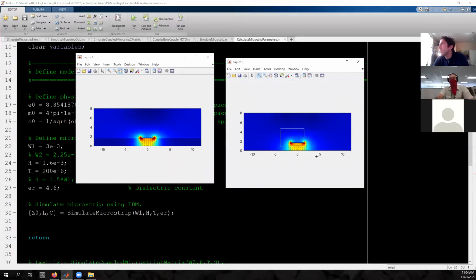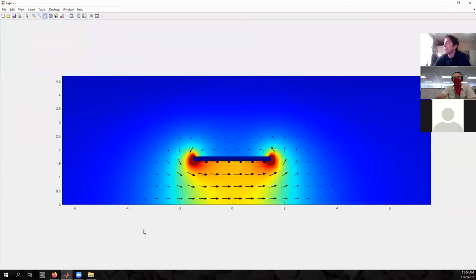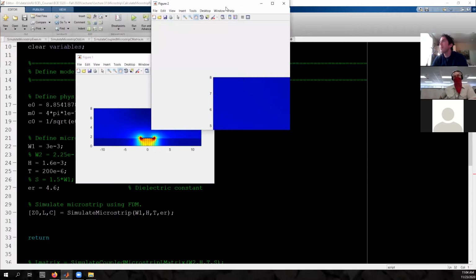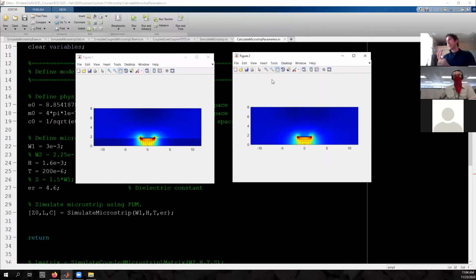And then over here, you can see I'm just doing the magnetostatic. So it's the same idea. It's actually the same equations and everything. You just have to interpret them a little bit differently. But there is some current excited on this strip here, creating a magnetic field. So let's zoom in. You imagine your thumb poking out of the screen and you follow the right-hand rule there. And you can see the magnetic fields are twirling around counterclockwise. Okay, so I have an electric field and I have a magnetic field. That means I can calculate capacitance and inductance.